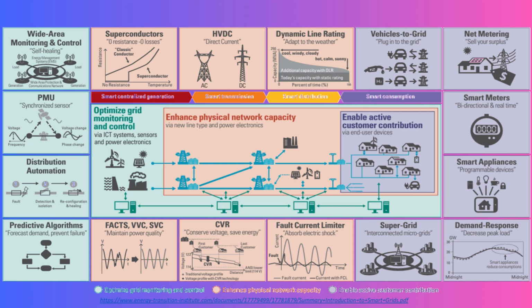and also for interconnecting asynchronous grids, like linking national grids that aren't perfectly synchronized. Another key tech here is dynamic line rating. Instead of having a fixed capacity limit on a transmission line, you use sensors to see how much power it can actually carry based on real-time conditions like wind speed cooling the wire. So you can push more power through existing lines safely. Exactly. It lets you squeeze more capacity out of existing assets, potentially delaying or avoiding the need for expensive new lines. It's about being smarter with the infrastructure you have.